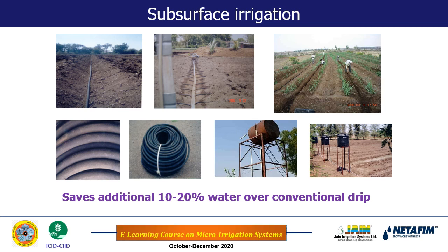The purpose is that in the subsurface irrigation method, as per its philosophy, water is to be maintained beneath the soil surface all the time. So in this porous pipe subsurface irrigation as well, water is to be maintained in the porous pipe all the time. Inside the pipe, water is maintained at full potential, and in the root zone initially the water is not at full potential. Therefore, water will seep from the porous pipe into the root zone.